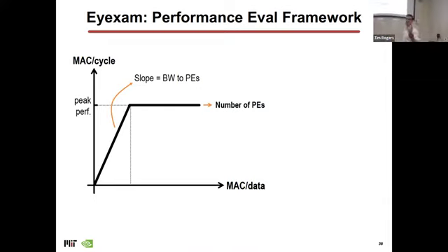So roofline is in that book because Patterson wrote the book, and Patterson, the student, proposed this. Probably we just haven't updated the slides to reflect everything that's in the book. So what is roofline? It's meant to be a high level estimate of maximum performance. I'm not going to worry about peculiarities of what's happening on each cycle. What I really want to know is how many MACs can I get per cycle? That is my parallelism. I have a bunch of MAC units. If they're all always doing something every cycle, then I'm good. I've hit the peak performance of this part.